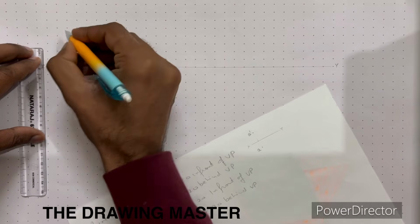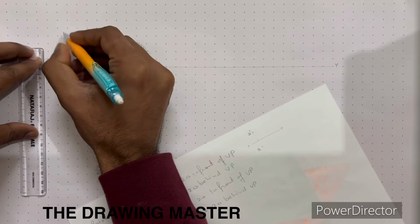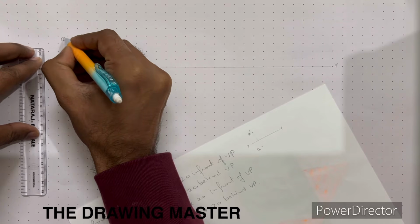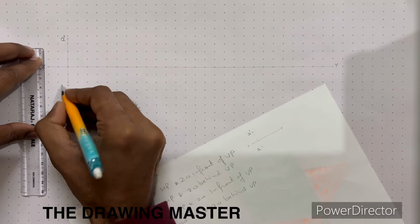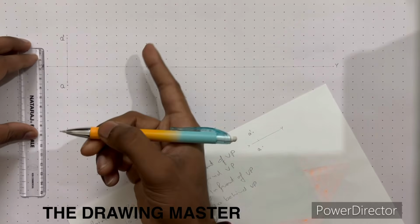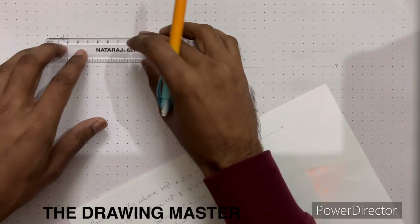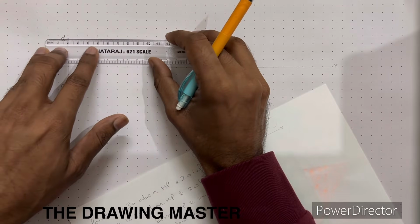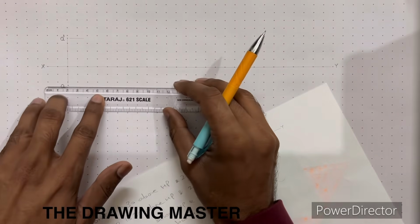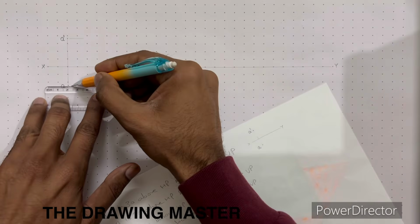This one is the top view. तो above means above the reference line, it is front view. तो notation क्या होती है front view की? Lower case letter with dash, and top view is lower case letter without dash. Third step: first step is the reference line, second step is the projection with label, and third step is the dimensioning. Dimensioning हमेशा लास्ट में करनी है. ठीक है, extension line. Take the extension line.